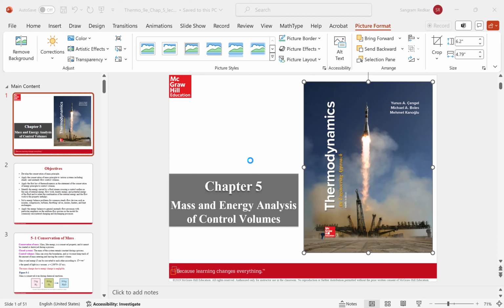Now, if you want to write conservation of mass as an integral equation, you will take an arbitrary volume, look at the boundary, and find out the total mass within the control volume, the mass that is coming in across the boundary, and the mass that is going out across the boundary.